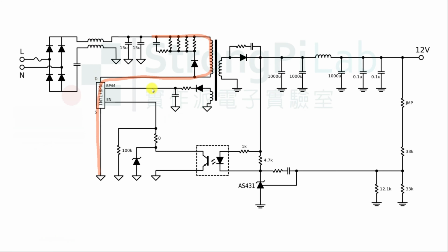Next topic is current IDS. We need a current probe. This is an expensive device. Even the differential probe I mentioned is expensive too. Basically you won't buy these expensive probes if you try to measure the switching loss just out of curiosity. How do you measure the switching loss using a general voltage probe?